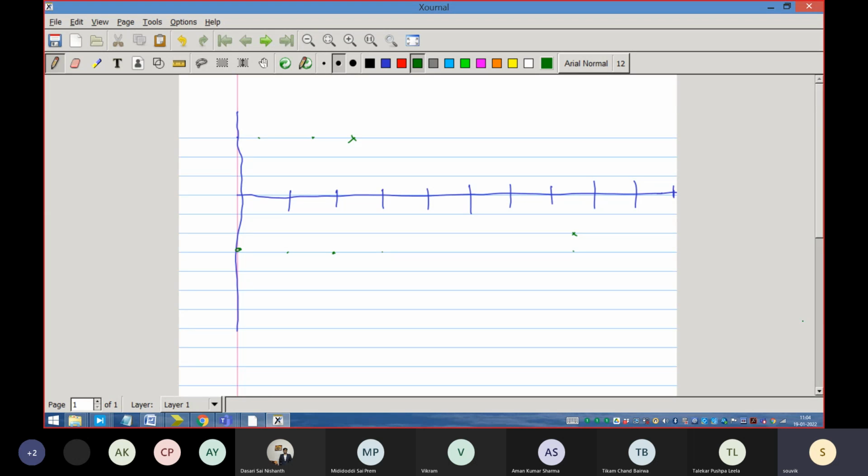They developed a modulation scheme called sine triangle modulation, where they scaled the quantities. They scaled the quantities, meaning the DC voltage was scaled as a triangular voltage. The peak of the DC voltage represented a triangular voltage. And why triangular, I had explained in the last class. A triangle is a kind of sawtooth function, and a sawtooth function represents the progress of time. If I want to represent time increasing by a waveform, then I must represent it by a sawtooth waveform.